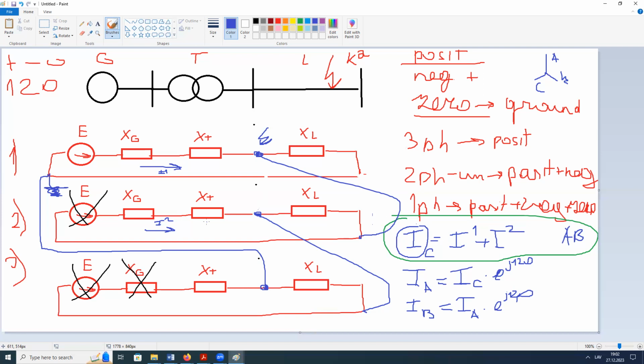Either we use a calculator that could operate with matrices, and of course with imaginary values, real and imaginary values, to calculate using this voltage potential approach all currents and voltages in this network. Or we use ready-made programs to draw the network, because calculating these values by hand is quite complicated.